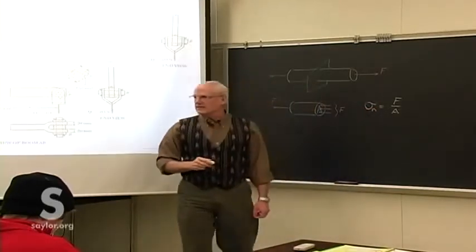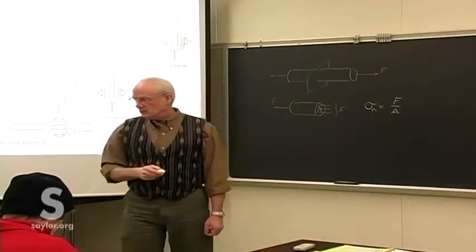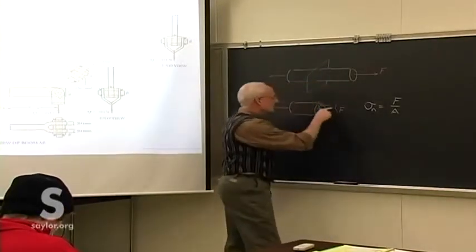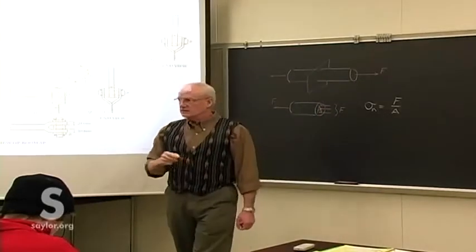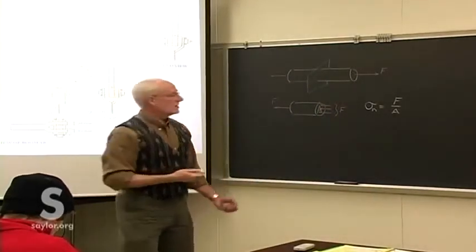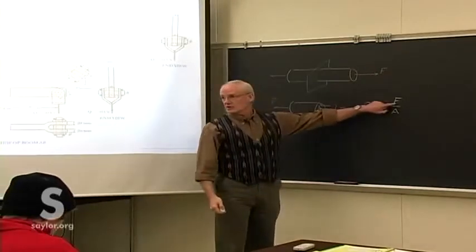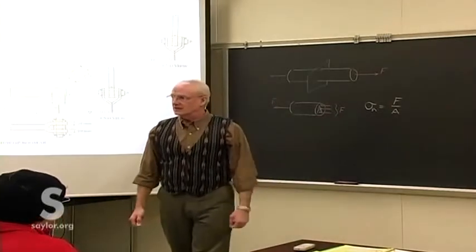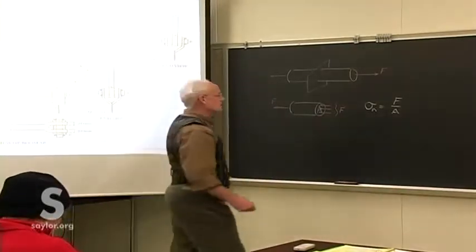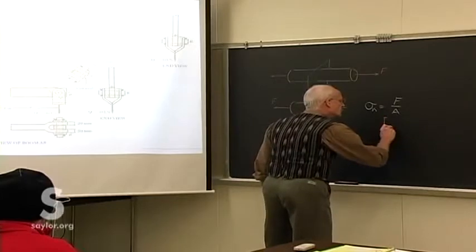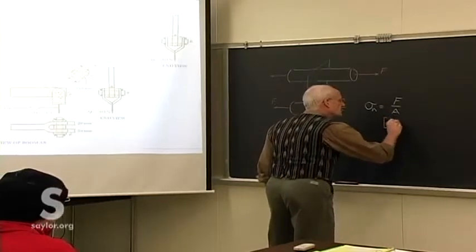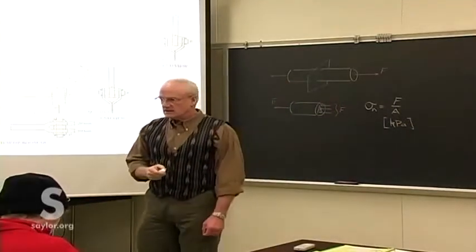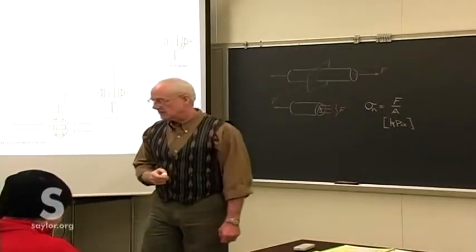Occasionally we'll put a little n there. If we don't, we're generally applying the normal stress. But we had that normal stress, the force divided by the area that's withstanding it, which kind of makes sense. As the force goes up, the stress is going to go up. As the area goes down, the stress is again going to go up. So it makes sense that we do this ratio. And the general units on this, typically kilopascals, maybe even mega, occasionally even as far as gigapascals.